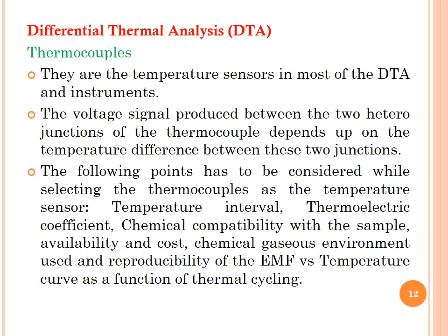Thermocouples. The thermocouples are the temperature sensors in most DTA, differential thermal analysis equipment, as well as other thermal analysis equipment or instruments. The voltage signal produced between the two heterojunctions of the thermocouple depends upon the temperature difference between these two junctions.